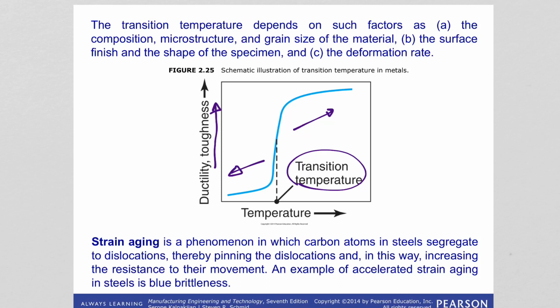They didn't take into account how the temperature would affect the material, so it didn't seal, because the normally very ductile rubber acted as a brittle material. It didn't do its job of sealing. So that's why the disaster happened. So this temperature is very important.